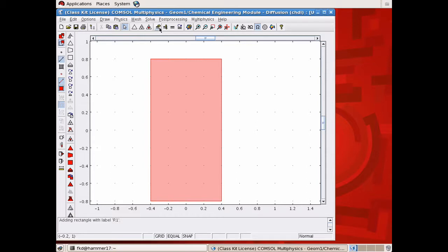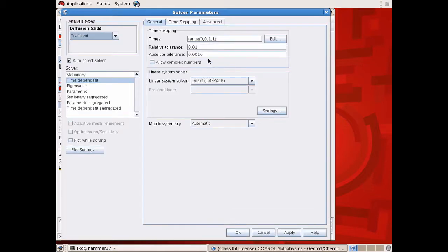And we're going to run it, but I guess we want to be able to do time stepping. So this is the initial time, 0, to time 1. Let's not do time 1, but let's do 10. And this is the time step, which is 0.1. I think that's all that is.